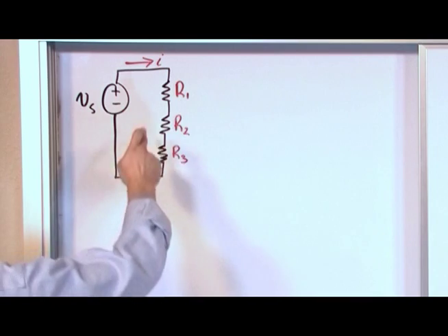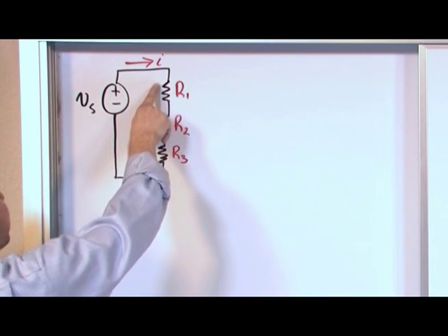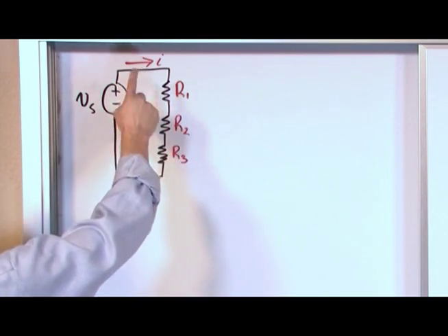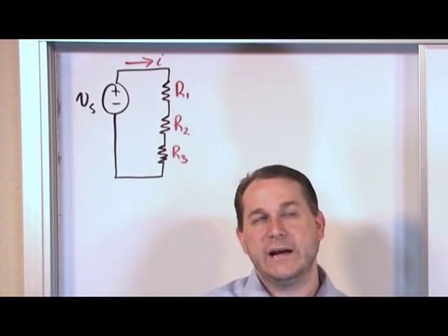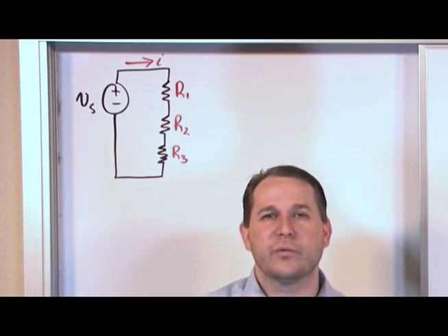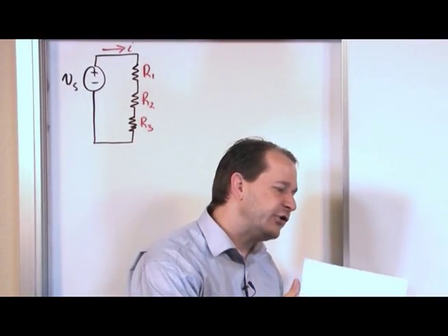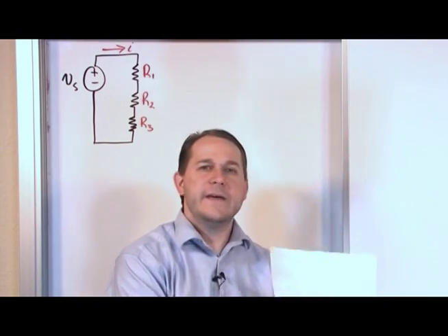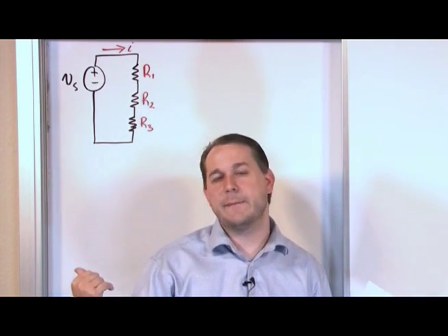When you have these resistors in series like this, what it means is the current that's flowing through them is the same current I all the way through, because there's only one path. You see, in a DC circuit, which is what we're talking about up to this point, the only way that current really ever changes is if it branches. When it hits a junction point and some of the current peels off this way, some of the current goes that way, then the value of those currents in those legs is different than what came out of the battery.